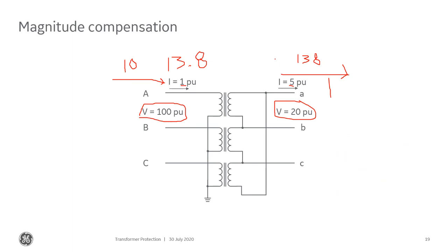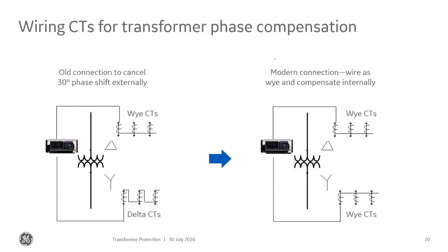Another thing that I really need to deal with also is zero sequence removal. So if I look at this transformer here, this transformer has a delta to Y conversion on it. So let's say this is a generating station and this is my generator sitting right up here. And that Y connected winding is sitting out connected to my transmission system. Now, the reason we have a Y connected, and this is a grounded Y, I'm not sure it is a grounded Y, but let's assume that it's a grounded Y.